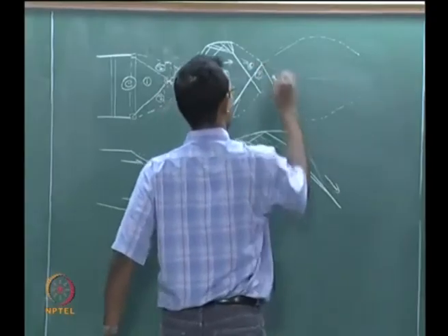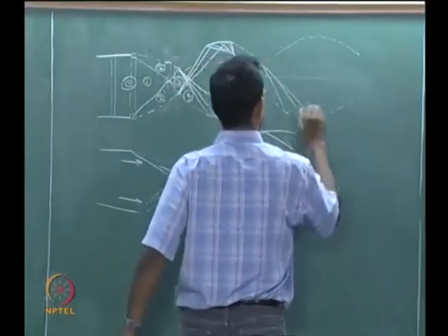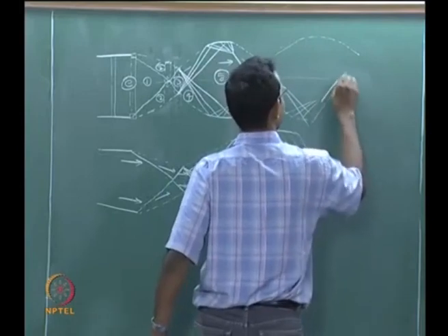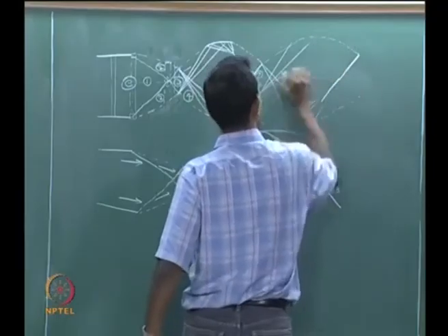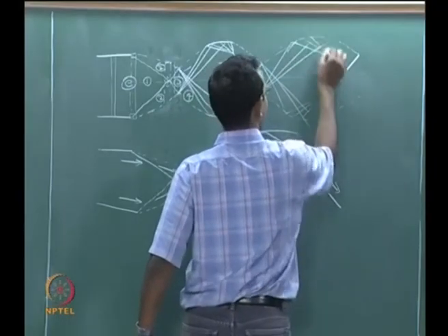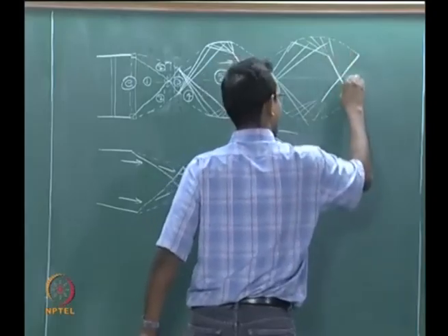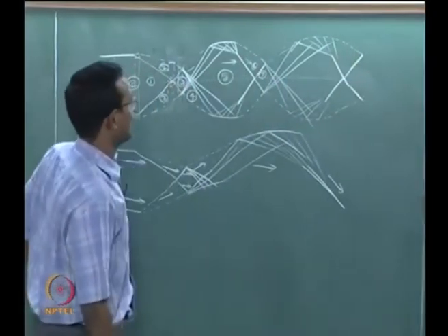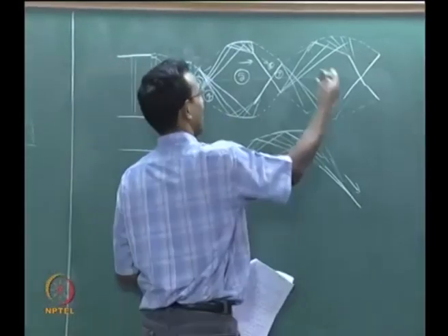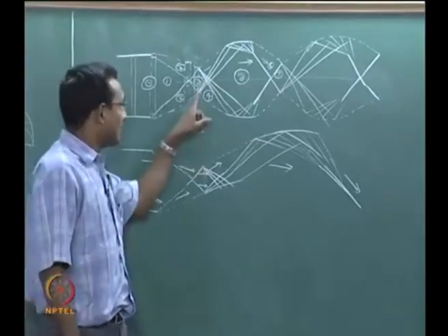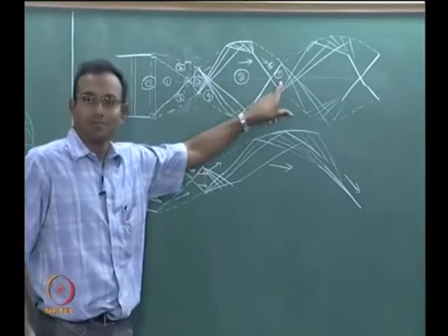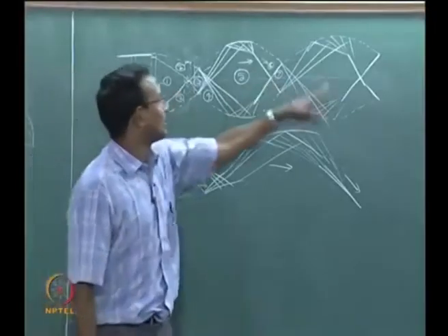If I look at what is happening inside, it's a whole bunch of expansion fans turning back to compression, forming a shock and crossing to that side. Same thing here, whole bunch of expansion turning back to compression, forming a shock and going to that point. That whole sequence happens again. If I want, I can label them again. It so happens that if we are in very ideal world, the pressure at 3 and pressure at 7 will be the same. If I do not have any other losses, it will be an exact repetition, okay? And it just keeps on going like this.